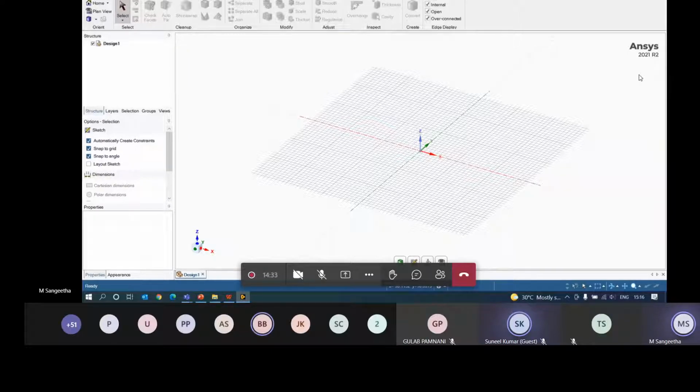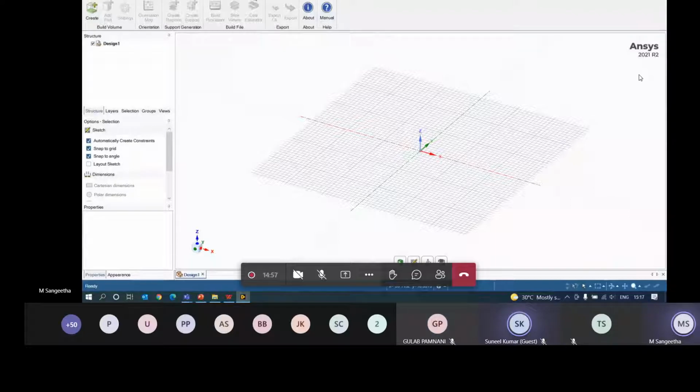There, first you'll perform structural analysis, then you will get the zero stress concentrated region, and that STL file you'll take for design optimization, and take it into SpaceClaim, where you have to give some smoothing to that geometry, right? So there, the facets you can use to work on it. And also you can work on additive related problems. Either you have to create the support or orientation. If you have to modify, in that case the additive tab can help you out.